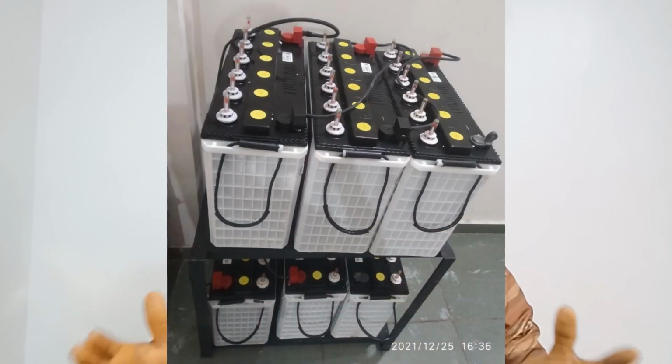Under lead acid technology, we have the flooded lead acid battery. The flooded lead acid batteries are those type of lead acid battery that have liquid electrolytes. They are a type of lead acid battery that requires maintenance, such as equalization, topping up with distilled water when necessary, and cleaning up the terminals of the battery when acid settles on it.